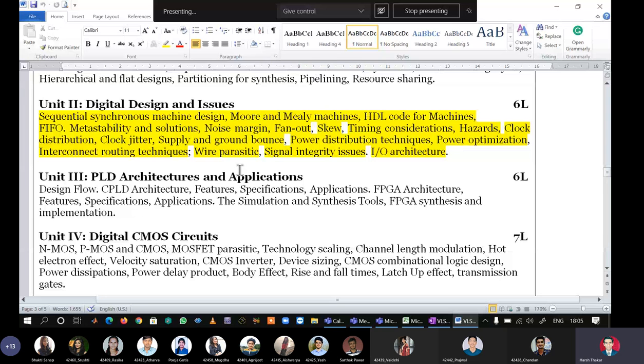That is writing the main model using VHDL language, synthesizing it, seeing the RTL schematic, seeing the technology schematic. After that, writing the test bench model, simulating it, and through waveforms, checking if the functionality has been achieved as per the truth table or function table. And the third step is once the functionality has been verified, then you use a floor planning tool such as PlanAhead. After that, you do pin locking and then you download the bit file into an FPGA. That is nothing but design flow.